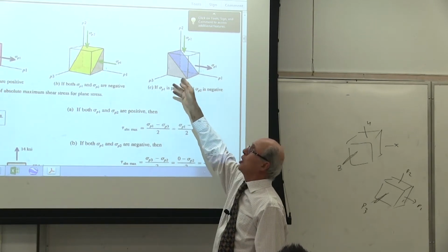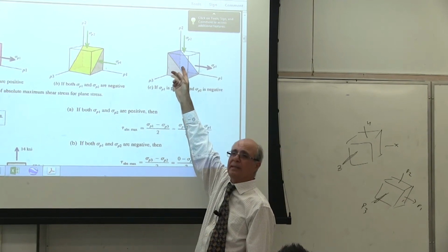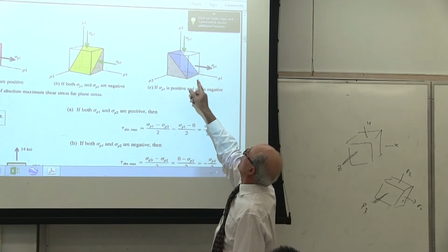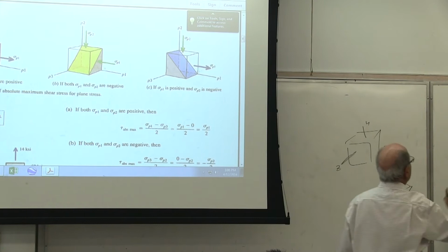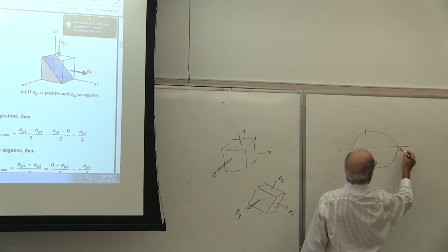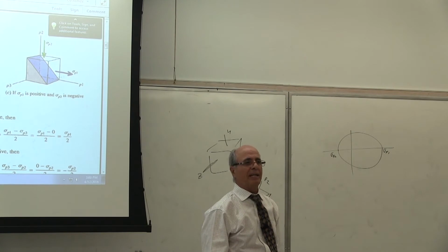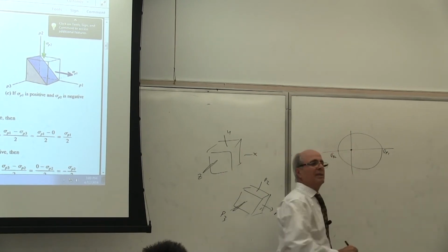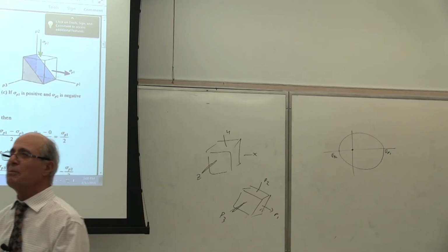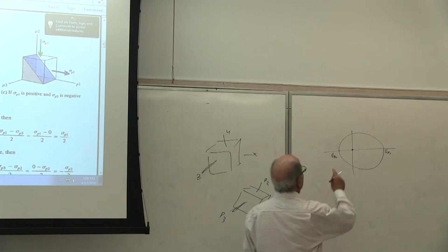They showed you the type of stress you get for the shaft and beam. Always one is positive, one is negative. This is always typical. You didn't know that, but that's what was going to happen. Therefore, when you draw the circle it becomes like this. The circle becomes one like that, because sigma principal 1 is positive and sigma principal 2 is negative. Everybody understand that? Since sigma c is here, you don't have to worry about it. That's why we went through the design in ME218 without even mentioning any of this. Everybody understand that? Therefore, the other two circles become inside.